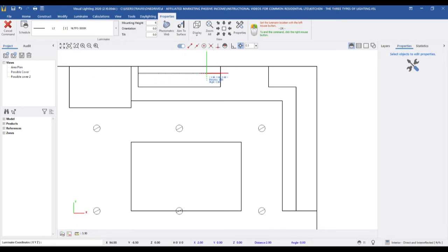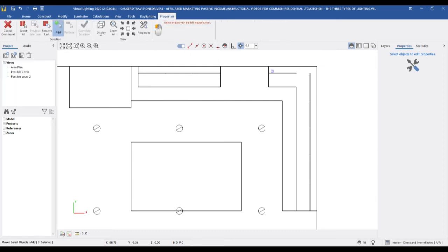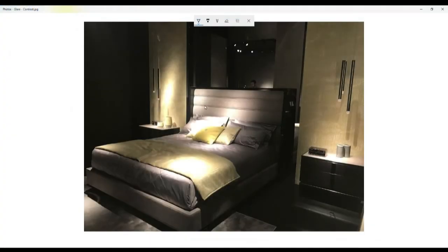When using this type of lighting, we want to identify areas where we will be performing a task or doing the most work, as well as the types of tasks or work being performed in that space. We think of this because in a bedroom, for example, a reading light is considered a task light. However, you don't want it to have too much center beam candle power or too much punch, so that it's so concentrated that you're trying to read and wind down for the night, yet it's so bright you can't even do that. The contrast will be too harsh on your eyes.